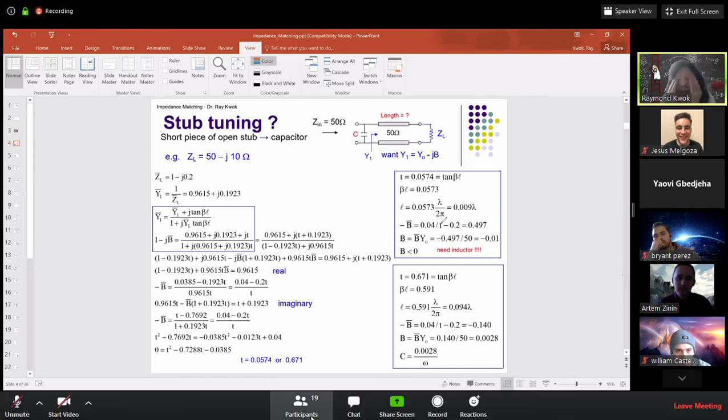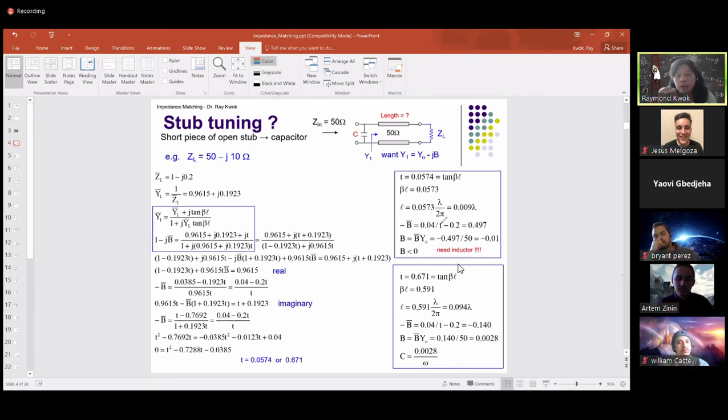That also ties to exactly what physically, what circuits you have. For high frequency circuits, a lot of times people use a substrate called alumina. Alumina is a white, hard material. It's not like Duroid 5880, which is very flexible.